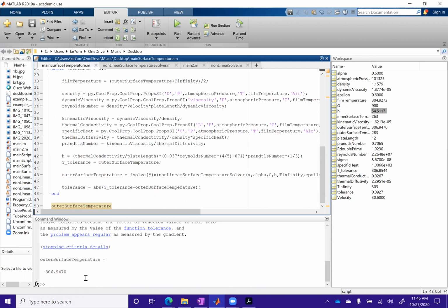So it changed 0.11 degrees. Really isn't that significant of a difference. So if you want to just always leave the 871, because if it's fully turbulent, then the Reynolds number largely takes care of that, and it's really not that significant of a difference, that's probably fine, just so you know.